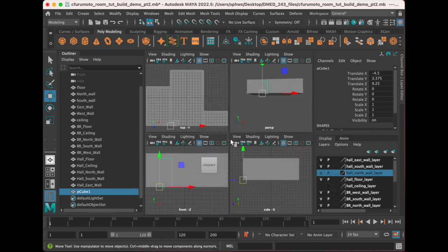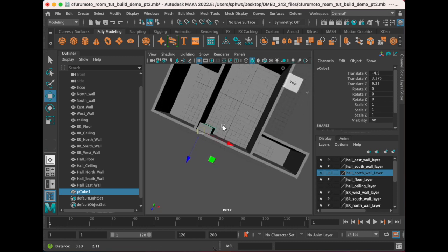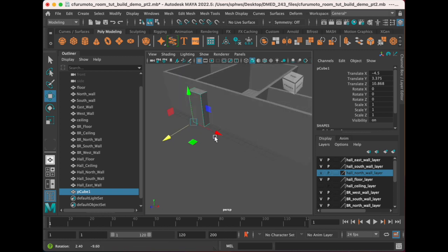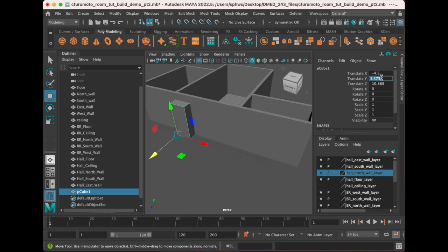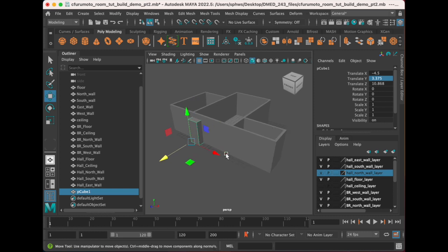All right, so that's another way we can get your object placed without having to do any math. We snapped it to the ground. If you notice, this is right on top of the grid. If you were to do the math, 6.75, this is half of that right over there, so 3.375. But we didn't have to do any math. For some people, that might be a plus.